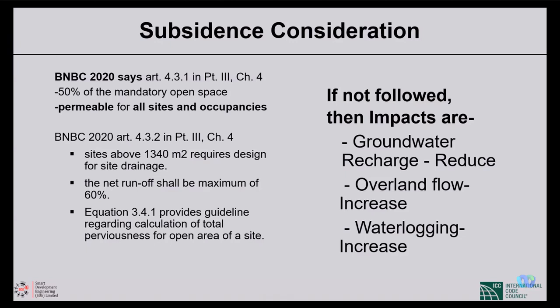That means more paved area, less penetration of rainfall, so overland flow will increase and flooding will increase. So keep the open space a minimum 50%. If I were president, I would say 70%. But we are in a crisis of land and we have pressure from population. This is the best that has been decided by our policymakers.